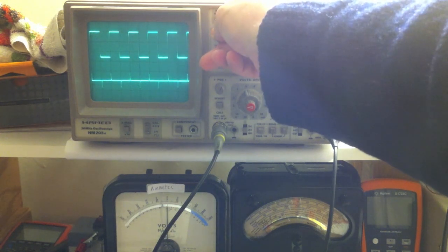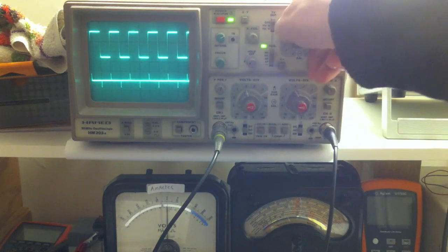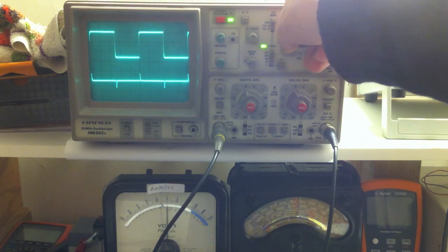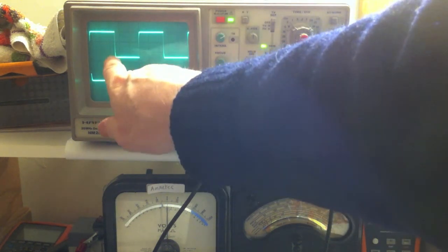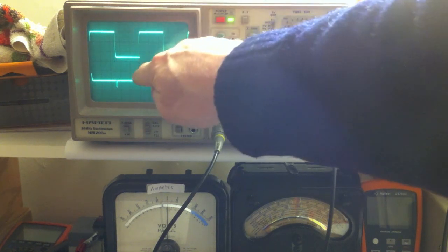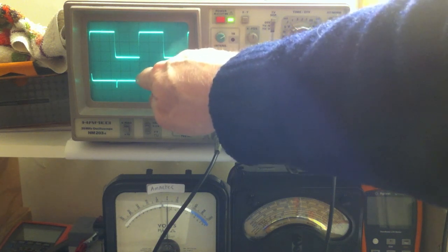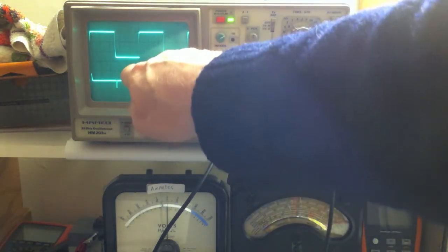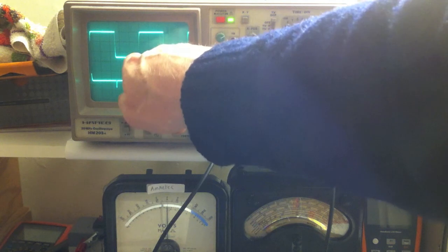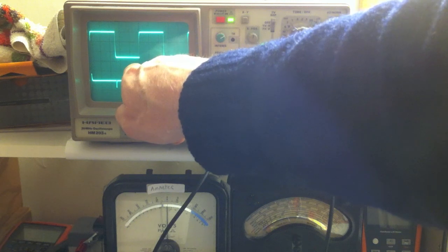At the moment, I don't know how well that's going to come out, but along the bottom here we see those exact spikes. Now I can reduce this down, I can zoom in and look at this a bit closer. So here you can see the spikes. For example, we're going from low to high in this square wave. We get this, the voltage across the resistor is peaked up here. Exactly the same thing. Now we can see the discharge, we can see the charging up of the capacitor simply by seeing how the voltage drops across the resistor.